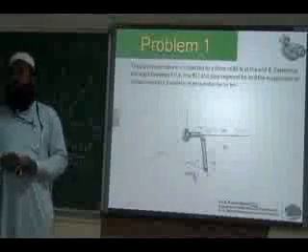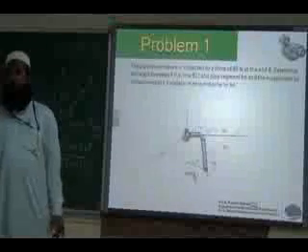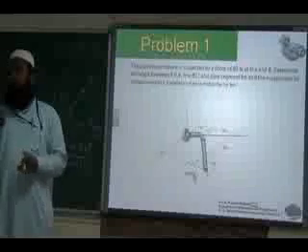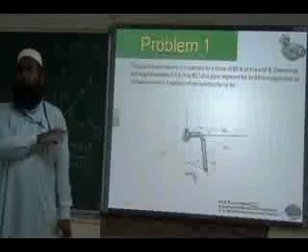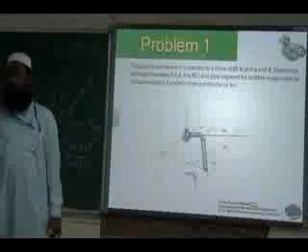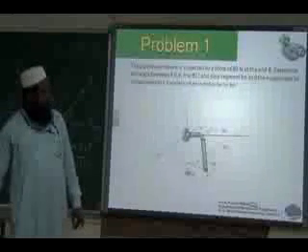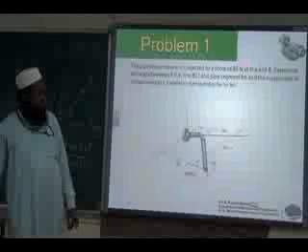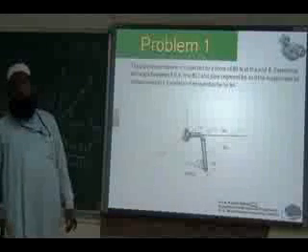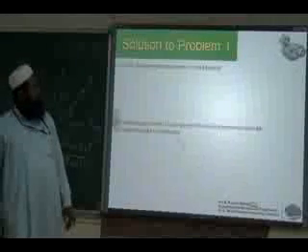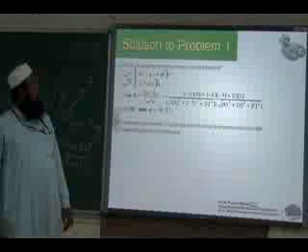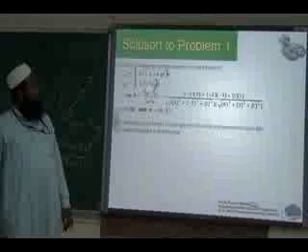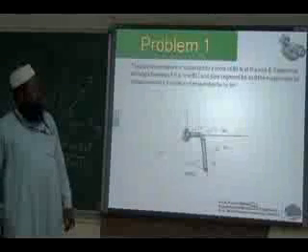To convert it to Cartesian form, we should know the position vector and find the unit vector, then multiply the unit vector by the given magnitude, and we will get the Cartesian form, isn't it? So we have to get the unit vector for BC as well as the unit vector for AB. That is the first step. The position vector for AB and for BC is found by considering the coordinates.